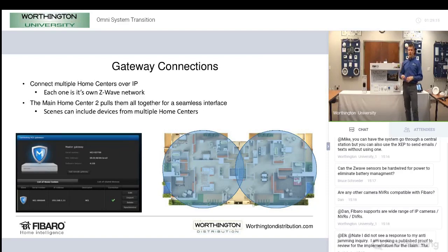One thing that gets into an issue with number of devices is the primary, or the hub in this case, will poll every device on that network periodically. So the more devices that are on there, the more of that given amount of bandwidth that we have ends up getting used for polling.